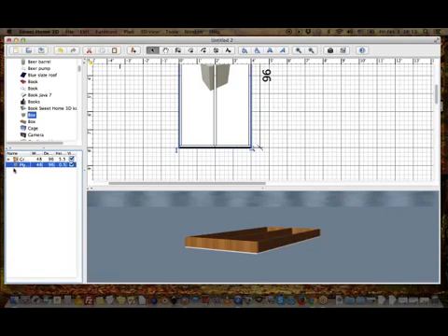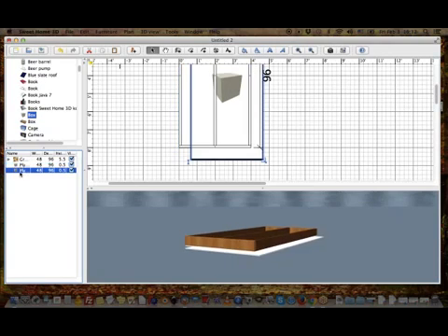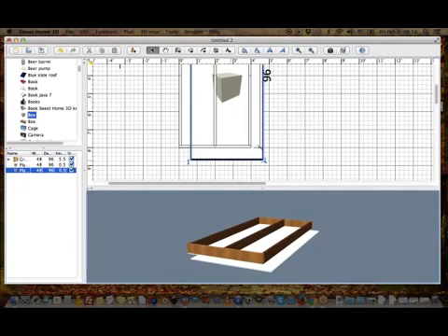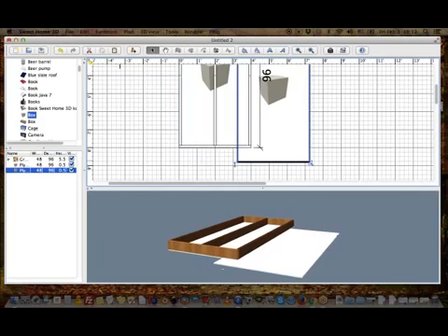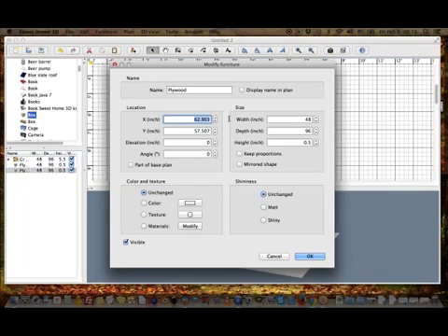Okay, and now I'm going to copy this one to make a second one for the top, right? So here's my copy. Here's the second one. But I actually want this to be on top. So once again, first I'm going to place it on the X24, Y48, and an elevation of 6. And how did I get to 6?